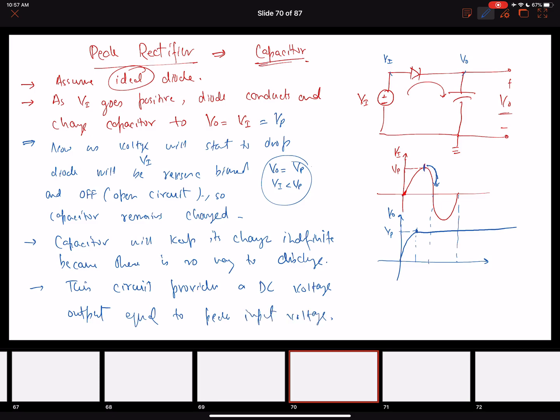All right. So this is again one of the very basic things. By the way, this is also known as a peak detector or a peak rectifier. It is called a peak detector because it is going to detect the peak and then remain constant. So again, in our case, after getting a full wave rectification of the waveform, we were interested in supplying a constant voltage.